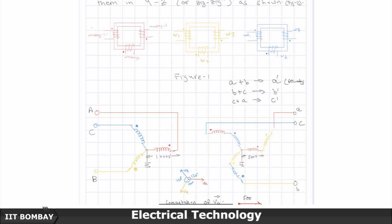Why do we do it? We do it for grounding. Especially if you have ungrounded systems, there may be problems of carrying third harmonic, sixth harmonic, triplen harmonics, ninth harmonics, and we want to give them a way to go to the ground, and we do not want to give a way for other things at the same time. We do not want to show an impedance path to the ground for the normal balanced voltages, otherwise significant current will start flowing.